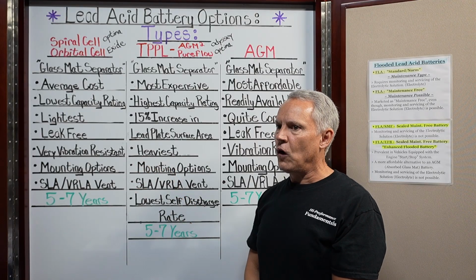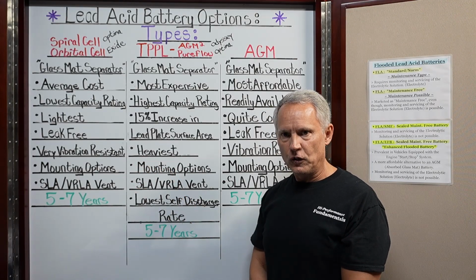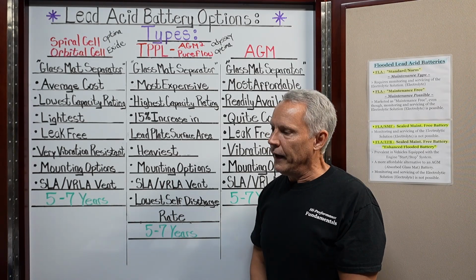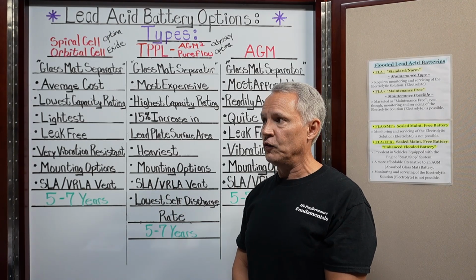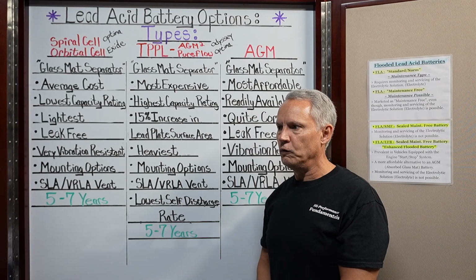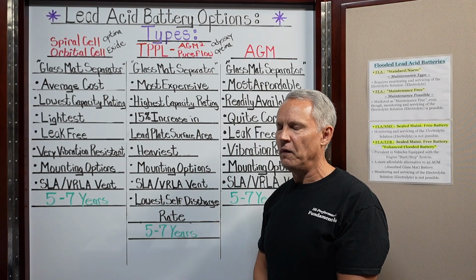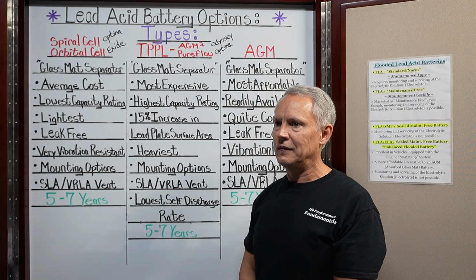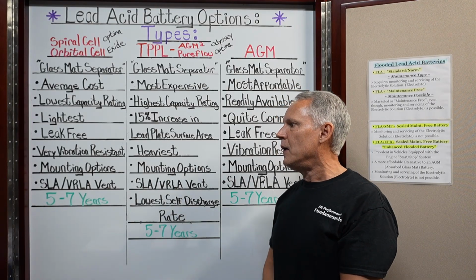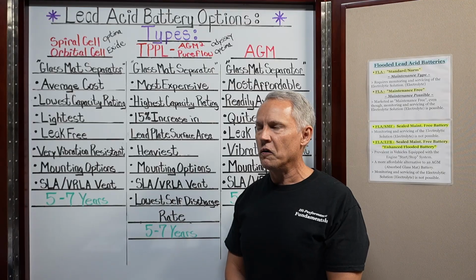A lot of these harnesses, you can't get a section. You can't get a piece. You have to get the whole entire vehicle harness. And in some cases, especially on German cars, some of the conductors are aluminum. So splicing in replacement harnesses can be very difficult. Now, you can do it to an extent, but it's difficult, and you have to be careful about liability when you start doing that. But it can range into the thousands of dollars.